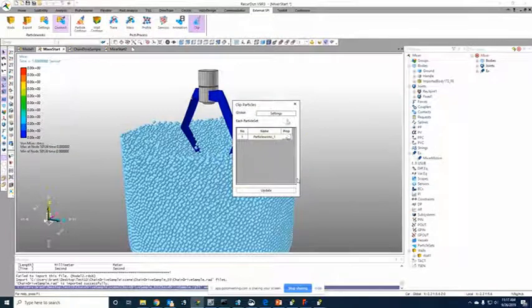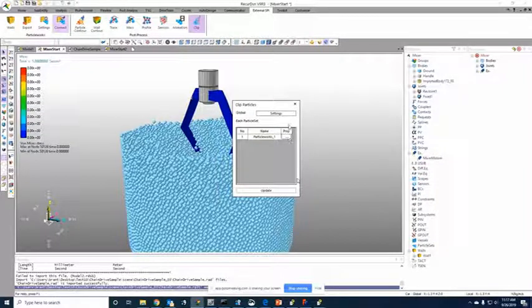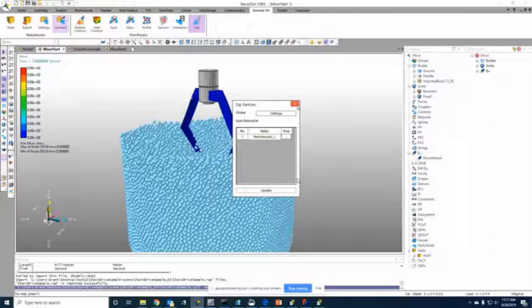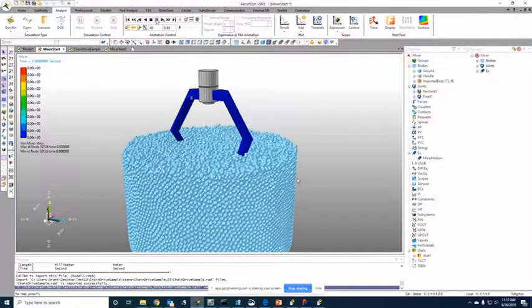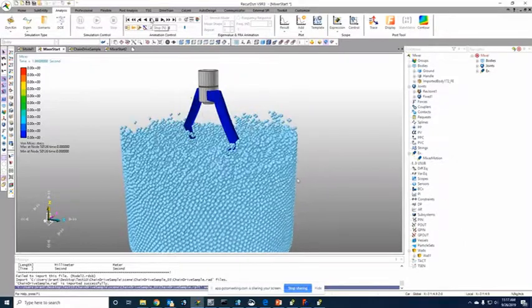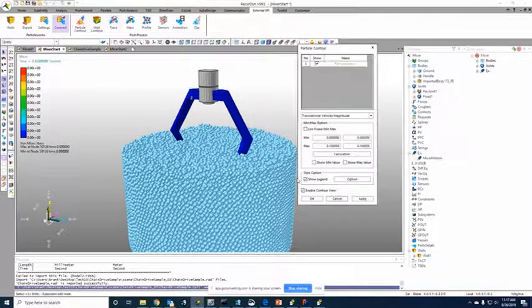Let's actually do something that we talked about yesterday and change this clip option. You can clip particles, and I had been messing around with this earlier, so I'm going to turn that off and we'll come back to it. So just the standard view right there, and then you can go into this and change the particle contour.